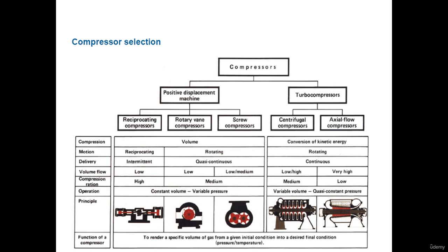So if you would like a high pressure, for example, the inlet pressure is 1 bar for the axial compressor, and you're asking for 14 bars, how many stages do you think you need? Maybe 12 impeller stages in order to achieve this from 1 to 14. While in a centrifugal compressor, maybe 2 or 3 stages is enough. And for reciprocating as well.